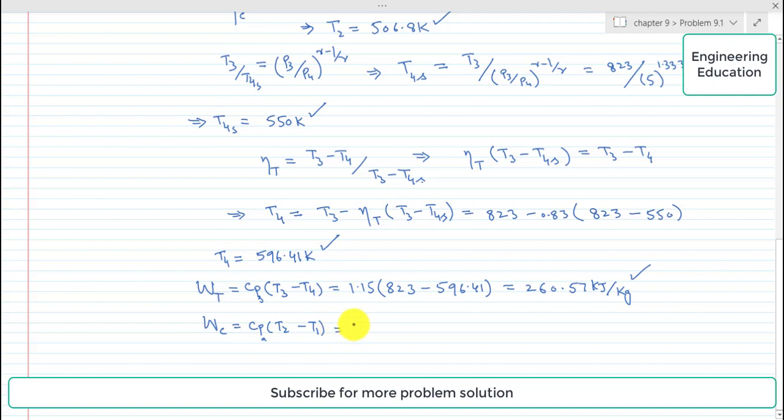So Cp for air is 1.005 kilojoule per kilogram per Kelvin. The value of T2 is 506.81 minus T1 is 293 Kelvin. So simplifying this, we get 214.87 kilojoule per kilogram.